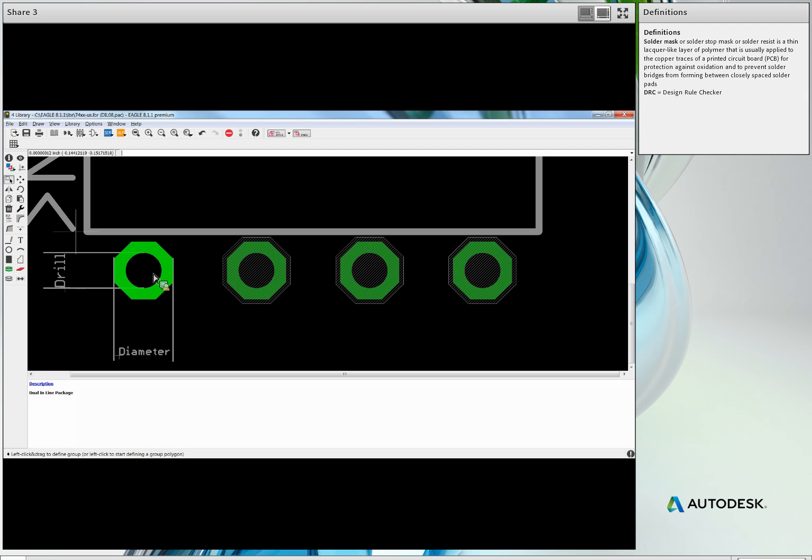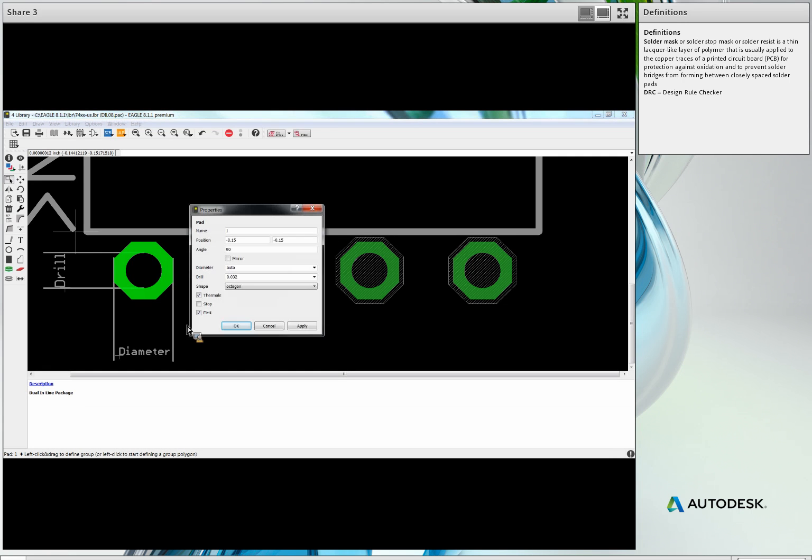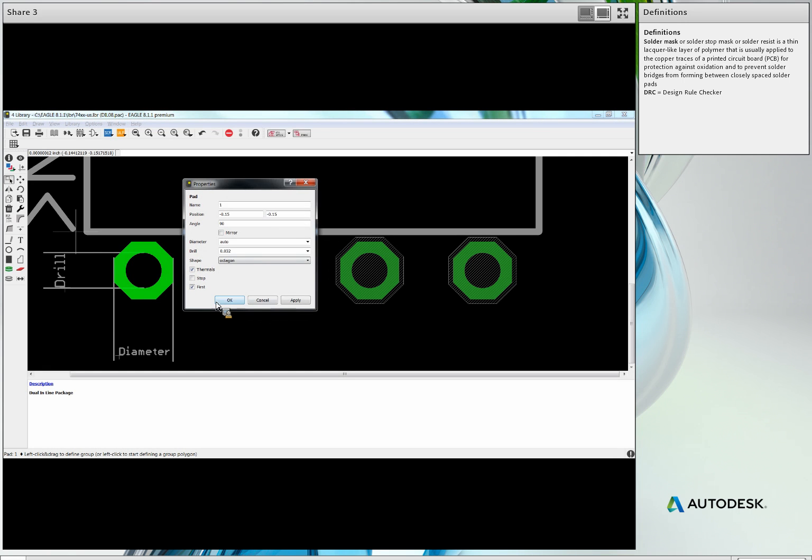There are some instances that this is actually good practice, or it's a practice that could be done, not quite common. Okay. Now, thermals refers to if you have polygons defined on your circuit board, if the polygon is actually going to connect to this pad using thermal reliefs, which are kind of like spoke-like wires, or it's going to connect to the pad by just simply swallowing it in entirety. Now, what happens is, and I'll be demonstrating this on the board in a few minutes as well.